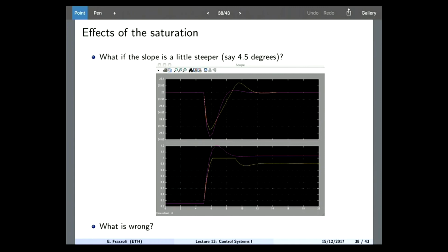Now, something that may happen, for example, on a car is the following. Now, your slope is increasing, okay? And your feedback controller is saying, okay, so I'm slowing down, so your integrator is building up, right? And then you start pressing the gas pedal more and more and more.